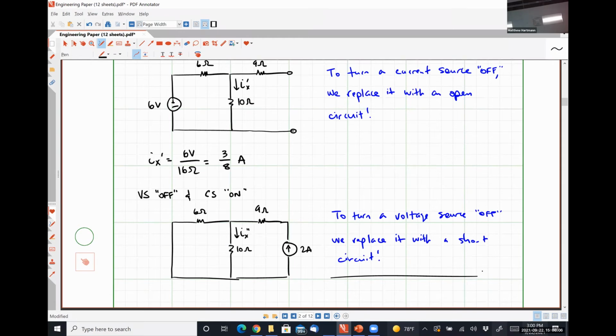How can I determine that current? Miss Miguez, sorry. How can we still have the current? There's voltage in the system, just not over that short circuit. So it's not a dumb question, but it is something that's kind of difficult to understand. You've got to think back to Ohm's law, right? V is equal to I times R. Well, R in this case is 0. So I can be anything it needs to be through a short circuit.